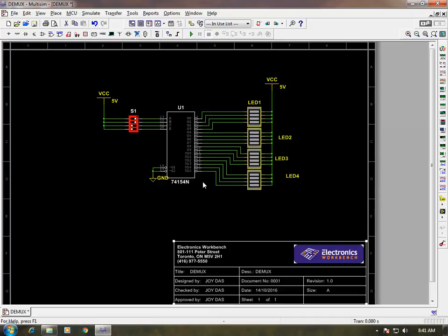One thing I should mention: the difference between 74151 and 74154 is that one is a multiplexer and one is a demultiplexer, but apart from that, 74154 gives an active low output. That is very important in digital electronic circuits. Active low is another state in logic design, besides high and low, and comes from the concept of tri-stated devices used in digital circuits.